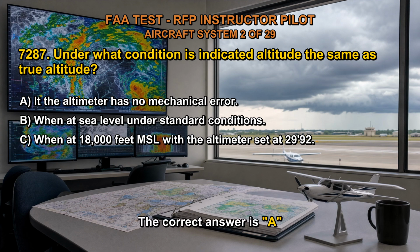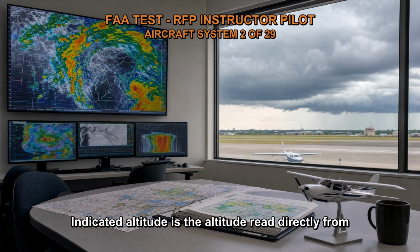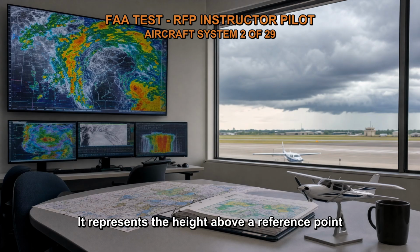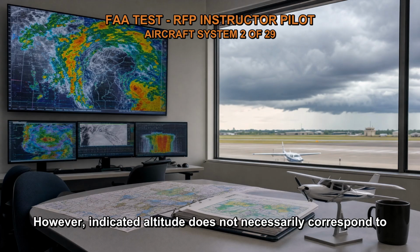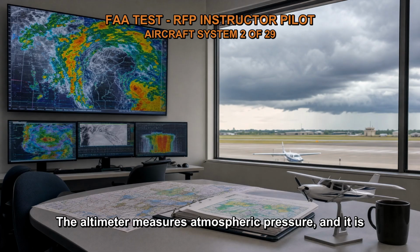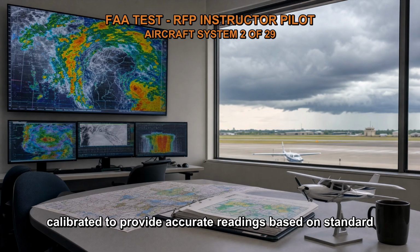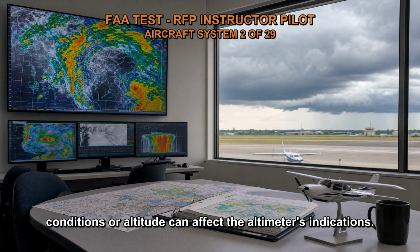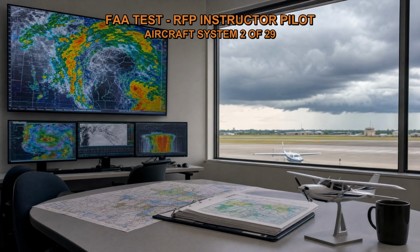The correct answer is A. Indicated altitude is the altitude read directly from the aircraft's altimeter. It represents the height above a reference point indicated by the altimeter. However, indicated altitude does not necessarily correspond to the true altitude of the aircraft. The altimeter measures atmospheric pressure, and it is calibrated to provide accurate readings based on standard atmospheric conditions. However, variations in atmospheric pressure due to weather conditions or altitude can affect the altimeter's indications.